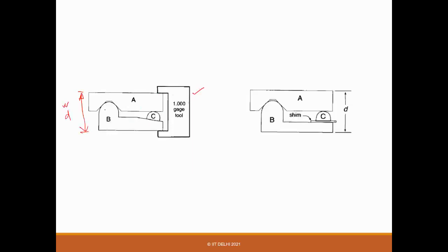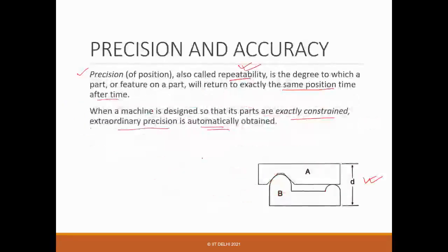So what has been done is, with the three contacts, you can get an exact constraint design, right? So you have C1, C2, and C3. What is the difference you see here? So we are talking about this case, right? Exactly constraint, right? And with the exact constraint, we will achieve repeatability.